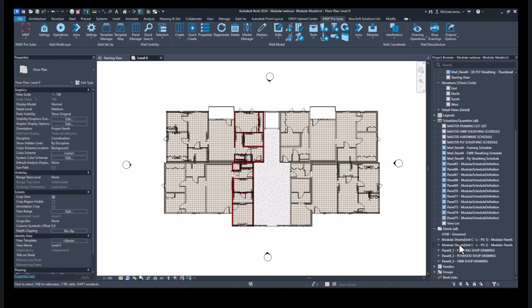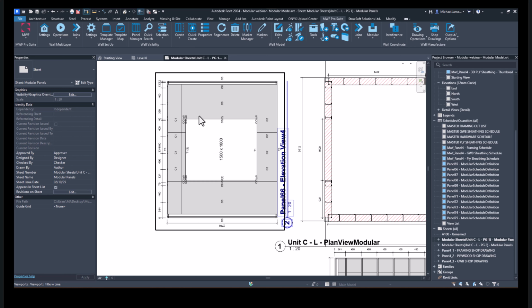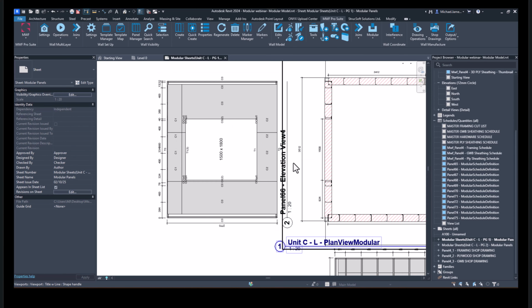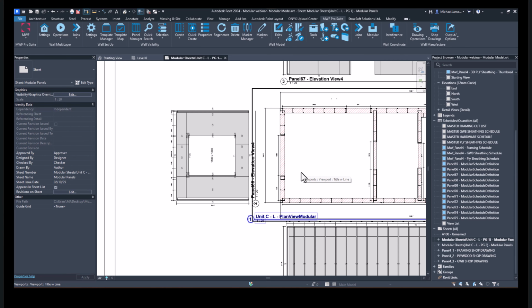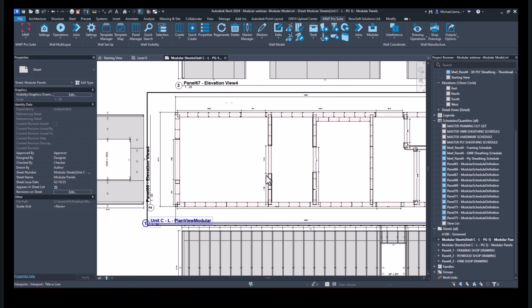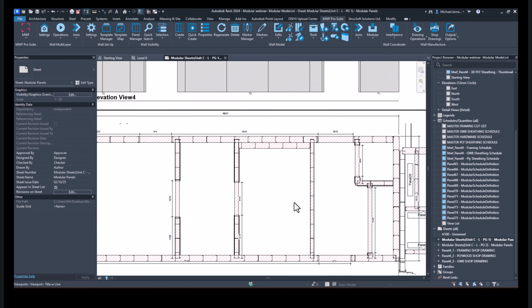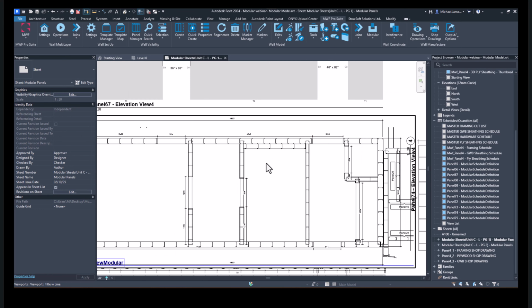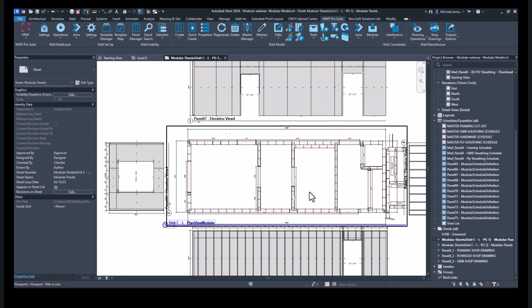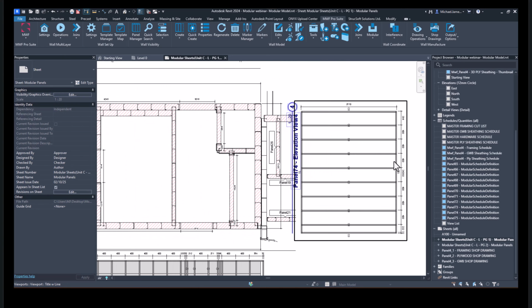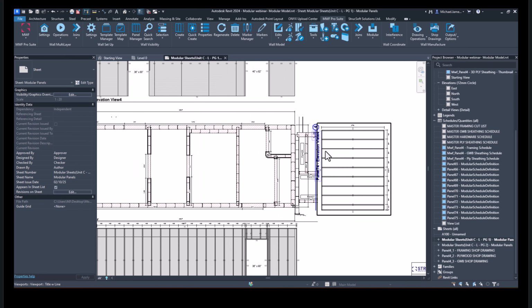You may need to play around with some of the visibility settings to ensure you get the kind of output you expect. You can see we've got our sheathing boards. We are labeling those members which make up the panel as well, so we have a number of cripple members, all of these different things which we can activate within our other sheet settings. In our plan view, this is also dimensioned based on the length of our panels. So we've got the overall length of our unit, overall width of the unit, and then we have just a structural panel here without the sheathing boards, as this one may not have sheathing on it anyway.